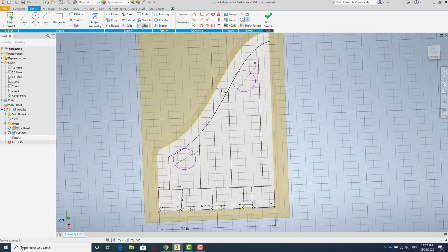Now we need to offset these either side, and that'll give us a good position to start with. Now I said I do want these to be quite thin, so we're going to go with a 0.5mm offset either side, and that will give me a 1mm key. Now since the last thing, let's go that one, yeah, 0.5, there we go. So do that for all those keys.